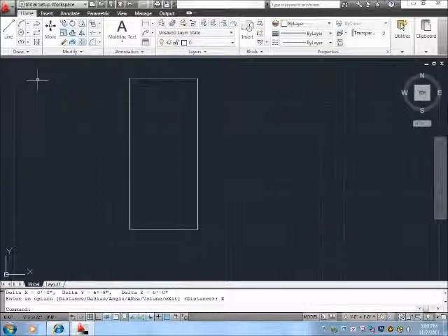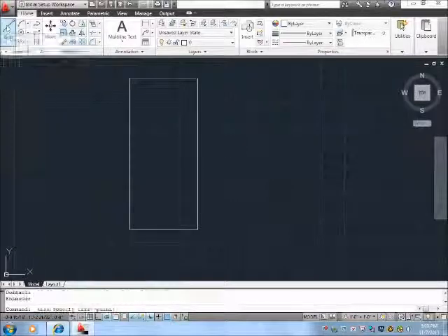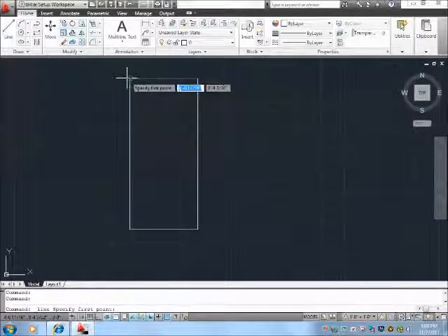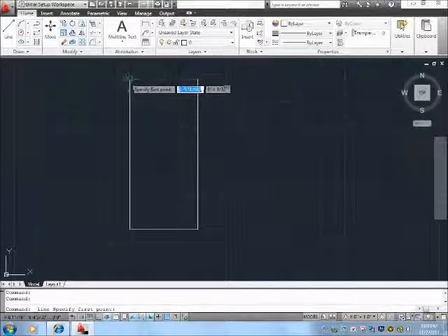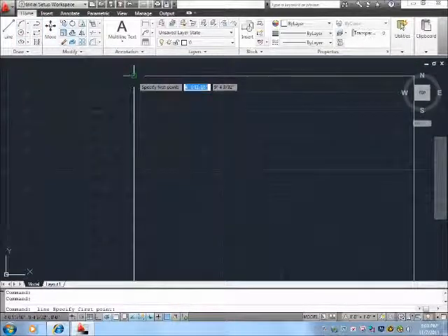So now I need to add the outside jambs of the door. And since they're outside, they're offset 4 inches to the outside. So 4 inches. Let me do this again so you can see it very clearly. I select the line. I'm going to zoom in a little bit on the top corner, and I'm just holding my mouse over that top corner until I see a green box.